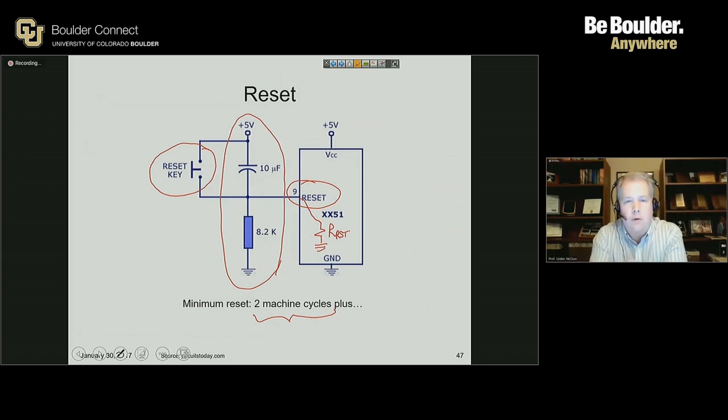That resistor is a diffused resistor that's in the silicon, and it is there to try to simplify our external circuit elements. If I don't have very particular requirements on the reset timing, and I just want low part count and low system cost, I might try to eliminate external circuitry, like getting rid of the external resistor and external reset line, and only connecting a capacitor to the reset pin. Because there's an internal resistor,